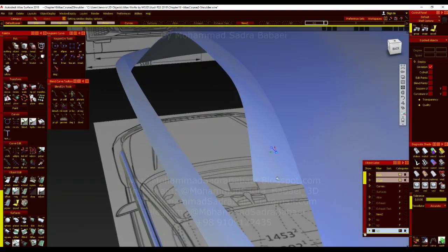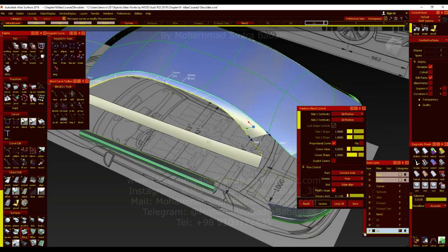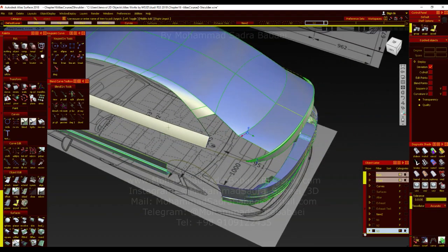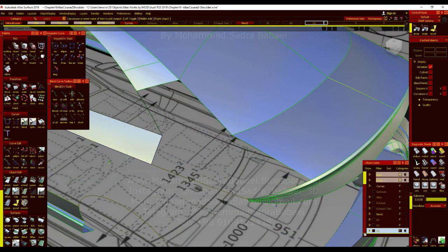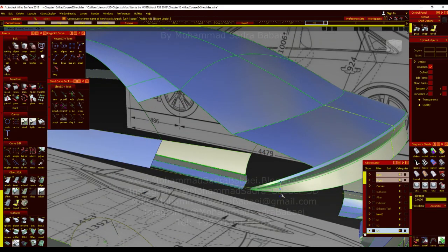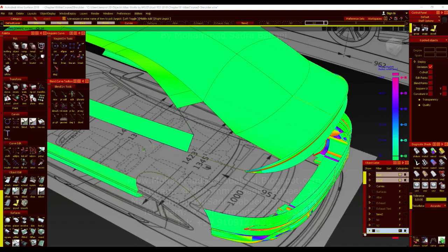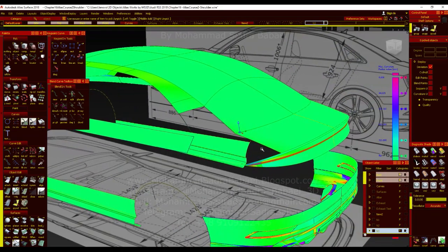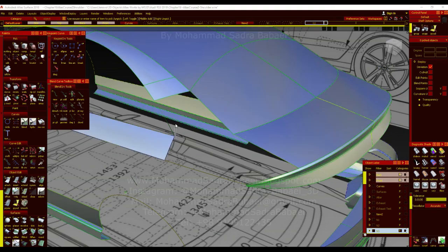As you see, this is exactly the crown that we wanted to create our model. Okay, this is the freeform blend which is created with chain select and a little crown. And now for this area we have explained some about this section, and we told you how to connect surfaces tangentially.